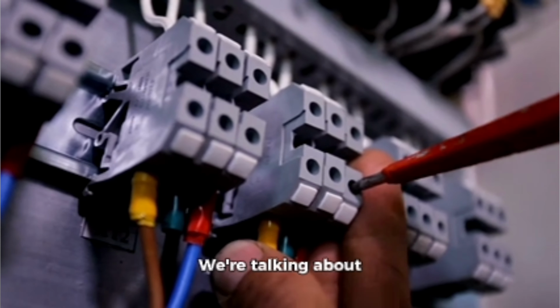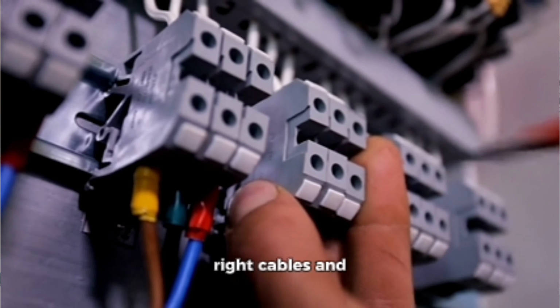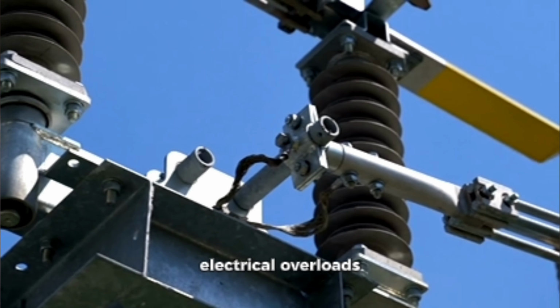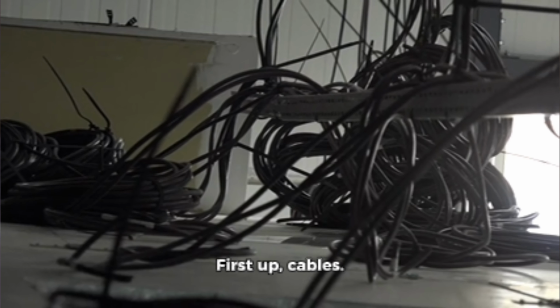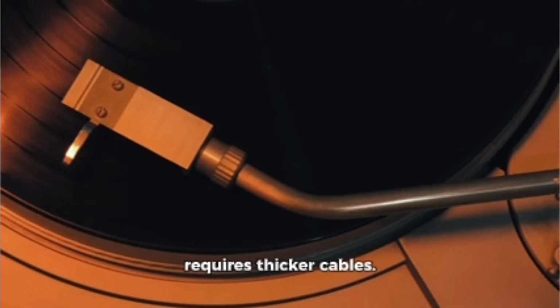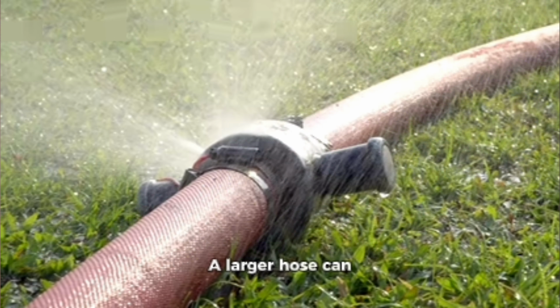We're talking about safety now, folks, and that means choosing the right cables and breakers for each circuit. These components are your first line of defense against electrical overloads and potential hazards. First up, cables. The size of the cable you need depends on the amount of current flowing through it. Higher current requires thicker cables. Think of it like a water hose. A larger hose can handle more water flow.